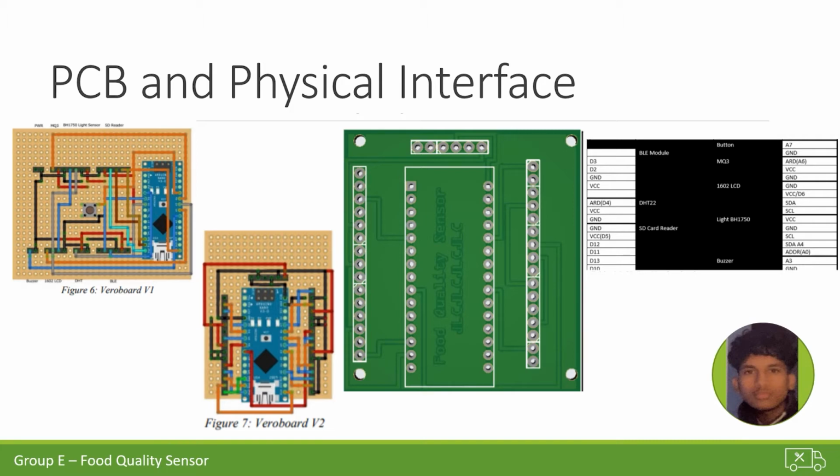The only problem that we came up with in the PCB design was the fact that the software only allowed for 2 layers for the routing, above and below. This meant we had to be very smart with the way we routed the product, but as you can see in the final PCB design on this slide, we use very little routing and the product is very compact, adhering to our design brief. All the components are close together, but not too close to cause safety hazard when soldering the components, and it created a very sleek design that fit perfectly into the box.